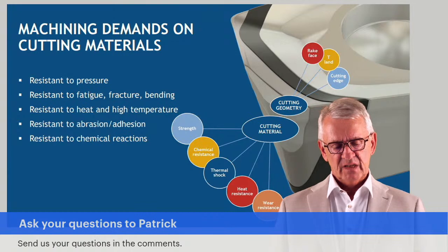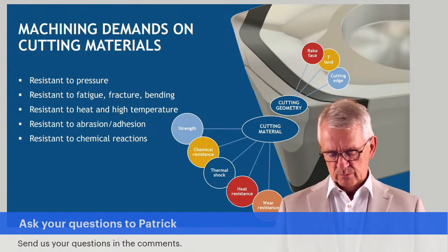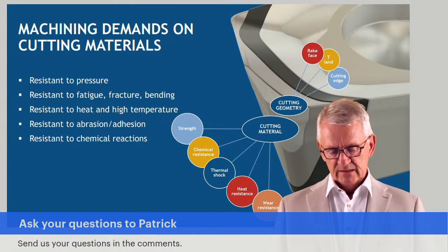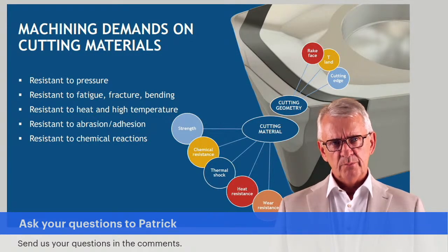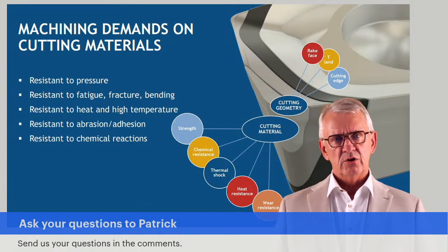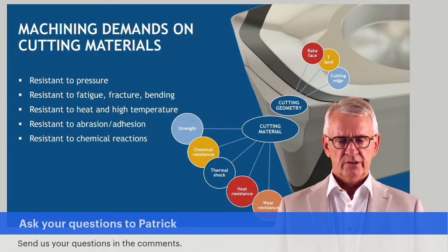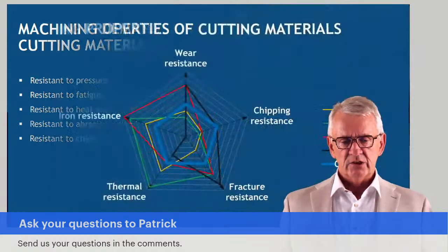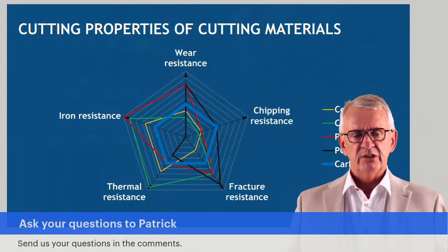I think, I don't know, perhaps Perola or Francesc would correct me when I say this, but I think fully exploiting the properties of CBN or PCBN also demands very serious thinking about the geometry you use on the cutting edge. But anyway, that's another subject. I just want to bring it to your attention.